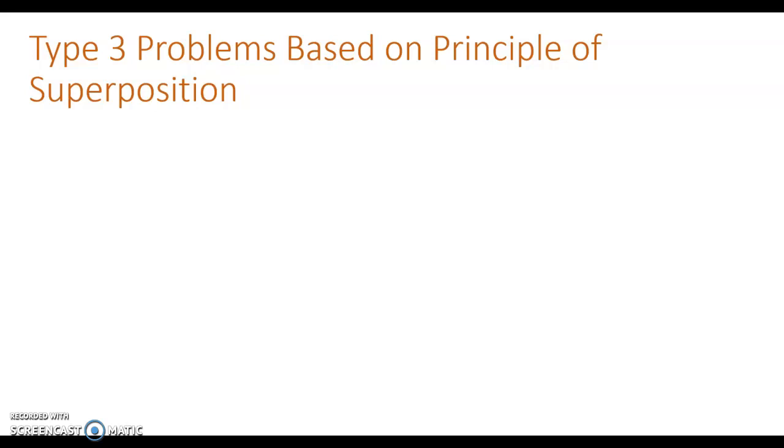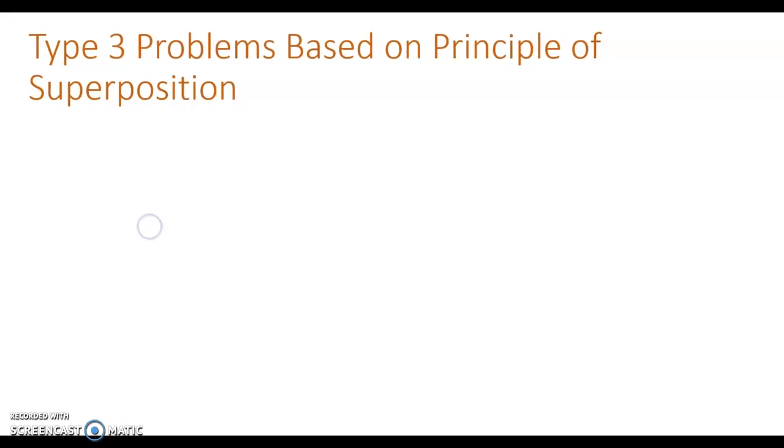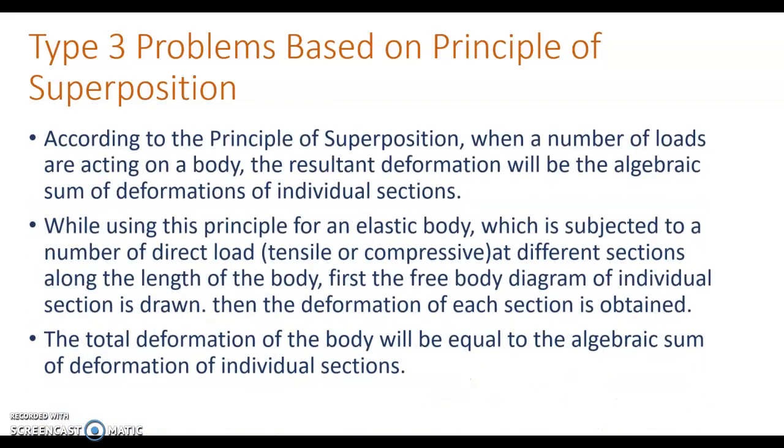Today we are going to see problems based on the principle of superposition. According to this principle, when a number of loads are acting on a body, the resultant deformation will be the algebraic sum of the deformations of the individual sections.